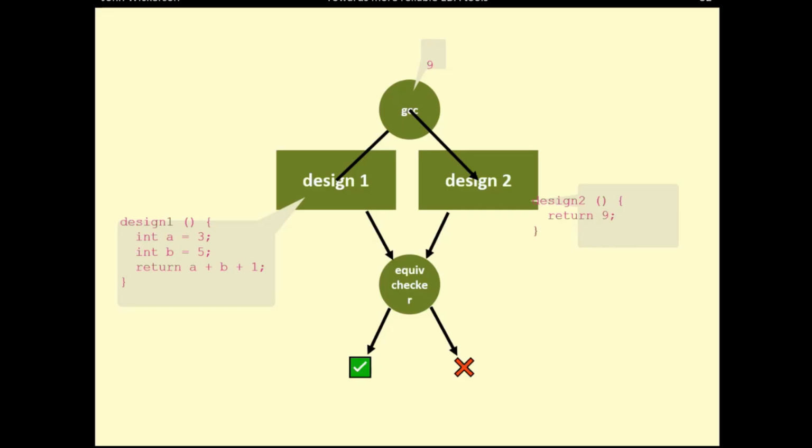We did this lots of times in the hope that sometimes we would get the equivalence checker to say no. But we were not entirely happy with that, even though we did find a few cases when it said no, when it shouldn't have. Because if the equivalence checker says no, that's a false negative. That's going to annoy the engineer. That's going to stop them proceeding to tape out. Which is bad, but it's not as bad as the other way around, false positive, where the equivalence checker says, yeah, you're good to go, but you're not, right?